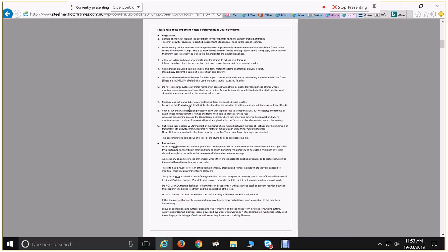It says things like, well, it's got its limitations for amount of roof load. I have to read through it quickly, but it will say roof loads not exceeding 6.9 metres or something at 2,700 high. So we go, okay, well, we wanted to do 3 metre high ceilings and we wanted to have a large roof on it. Can't use it. So a lot of your limitations are set out in here.